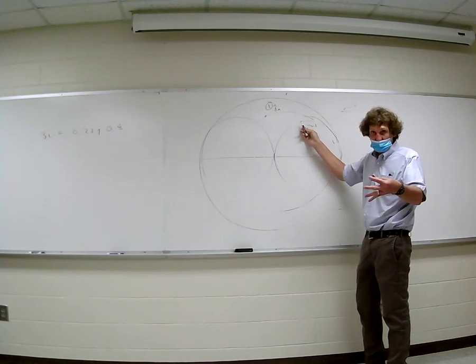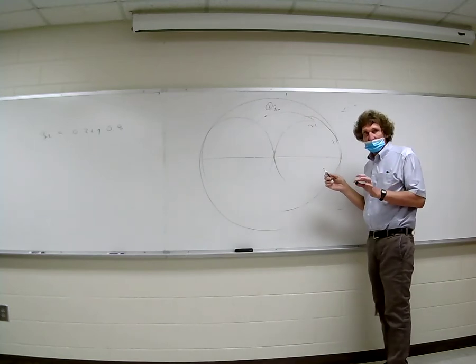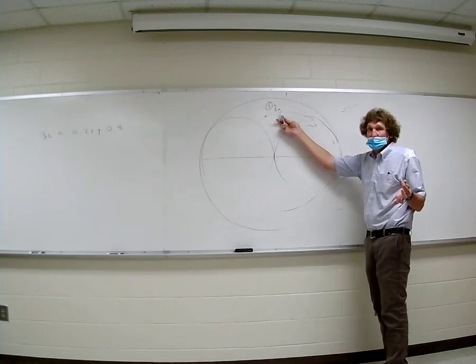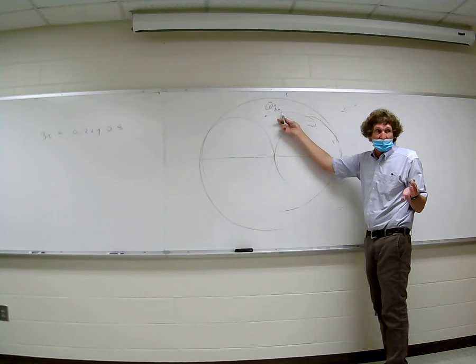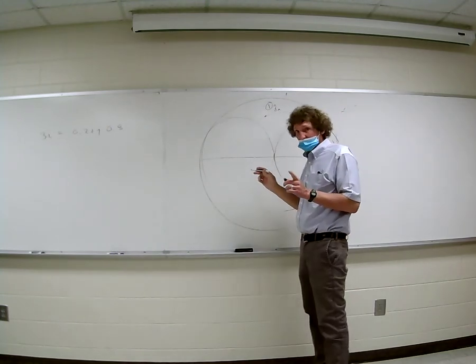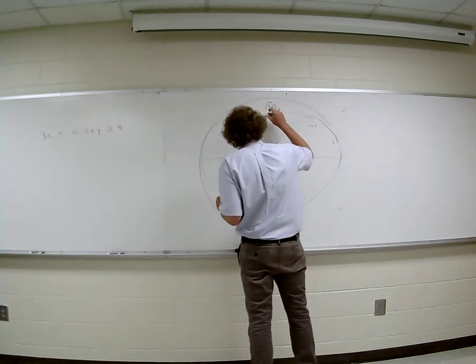You with me, everyone? Anything we add in series, we can just get rid of the j. It's 0.2 plus j0.8. So I could get rid of j0.8, I still got 0.2. It's not doing me any good, right? So what I need to do is add something in the admittance domain, right? And how am I going to do that? Well, now I'm going to come over here